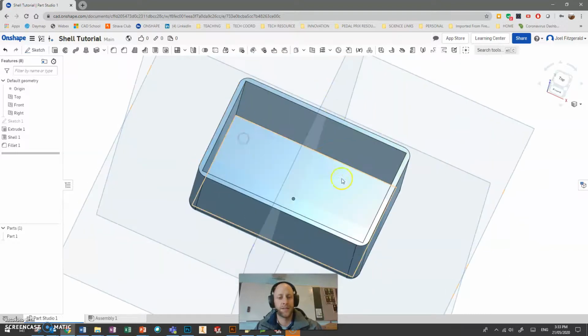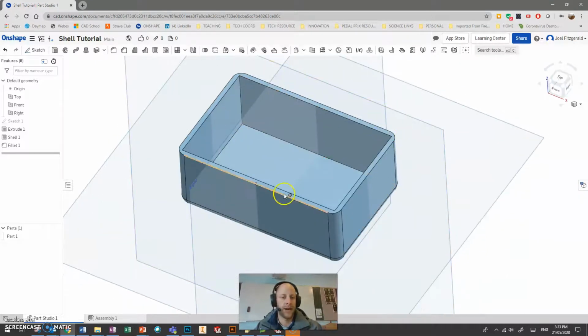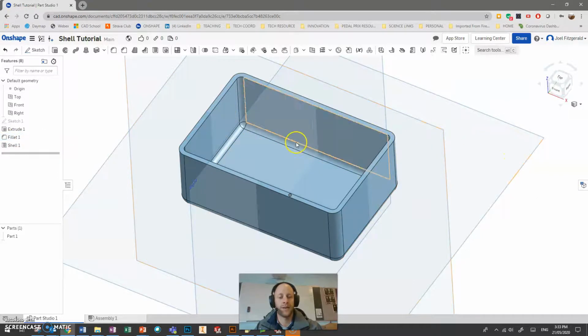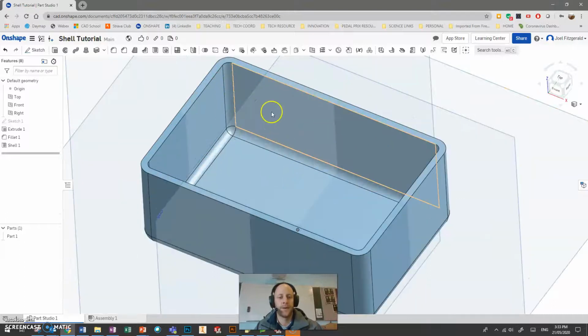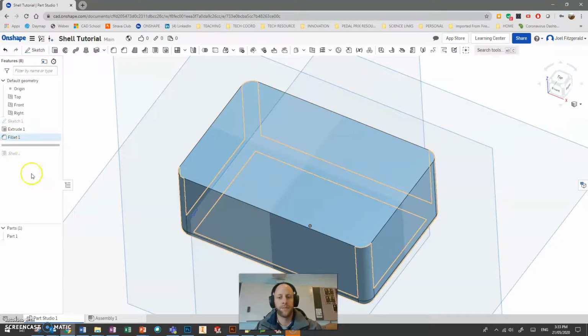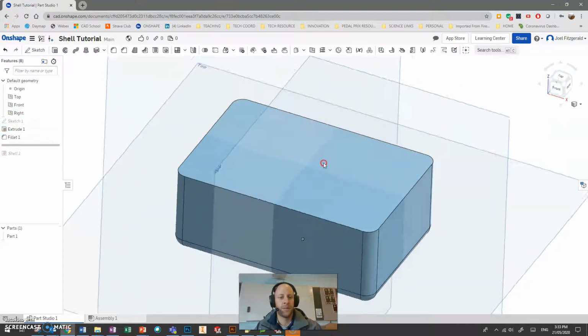So that's the slow way to do it. Add the fillet first, add the inside fillet. Now, if I simply reorder my fillet before the shell, you'll notice straight away that my part miraculously fillets the inside. And that's because if I go roll back, so I can pull this back into my model and have a look at it, this is the process by moving it backwards.